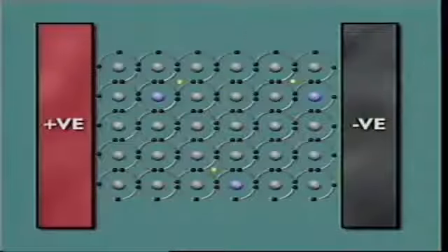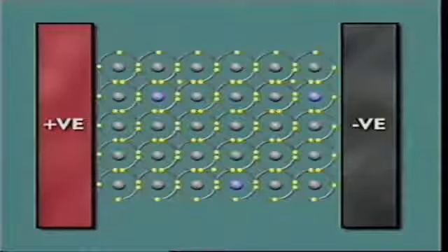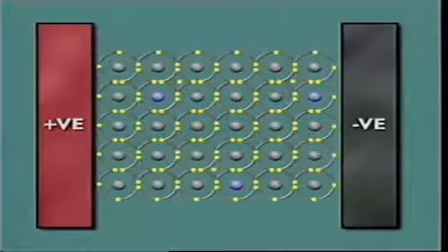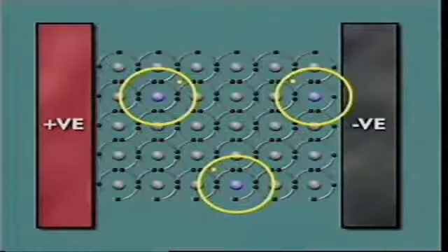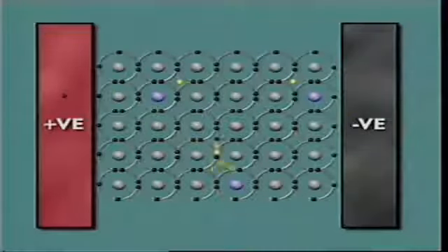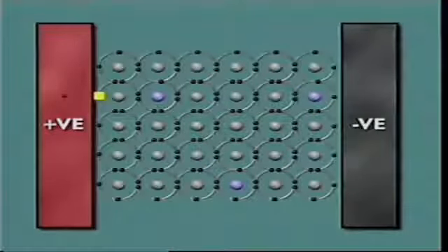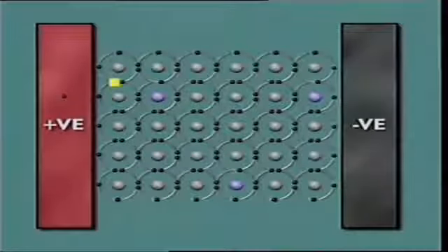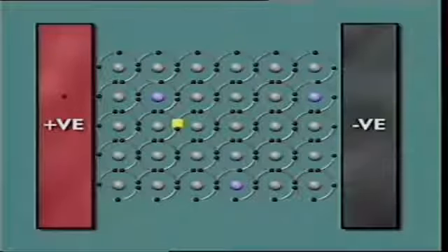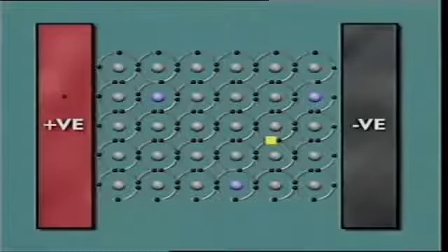A semiconductor's conducting ability depends on two kinds of charge carriers. The first is familiar, the negative electron. This kind of semiconductor contains an excess of free electrons. They can be made to flow and carry charge. The second type of charge carrier occurs from a loss of electrons, with gaps called holes, where the electrons were. Since negative electrons have been lost, they are called positive holes, and because they are positive, a voltage can make them move towards the negative pole.